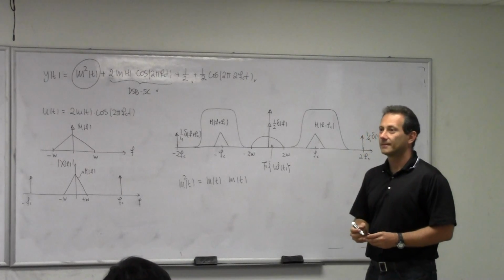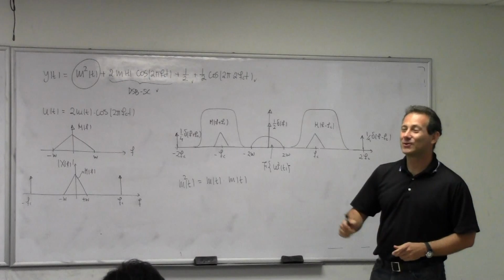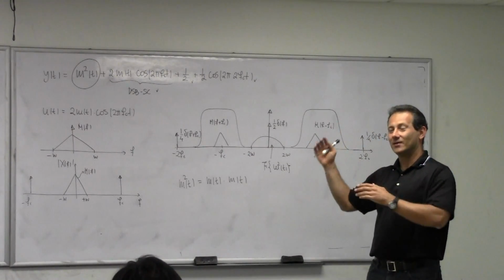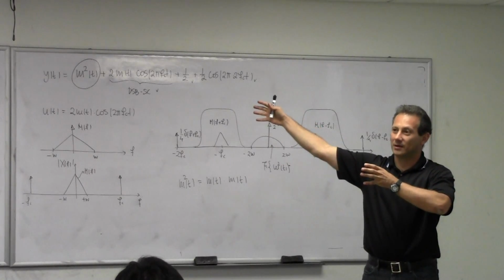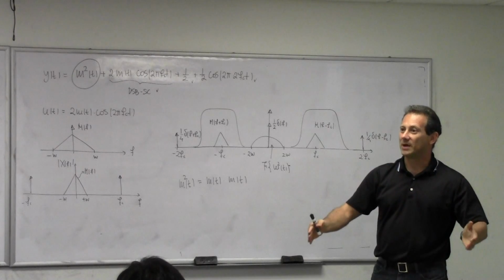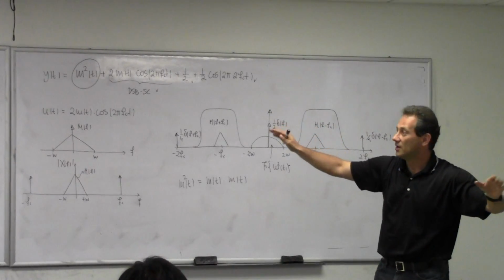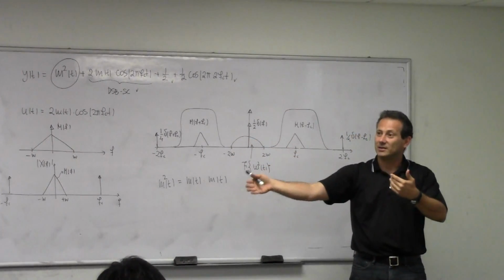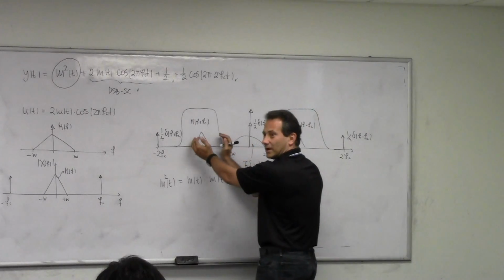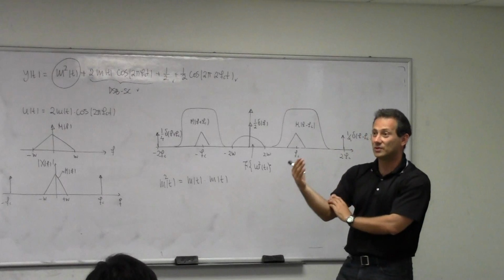Shams favors low pass, I don't know if you know this, because Shams looks at demodulation. I'm looking the other way around, right? When you go from the frequency of the carrier to the baseband, then you have to use low pass because everything else is extra. You don't need everything else. When you go from the baseband to the modulated carrier, then you have to pick the part that's around the carrier. So depending on whether you're doing modulation or demodulation.